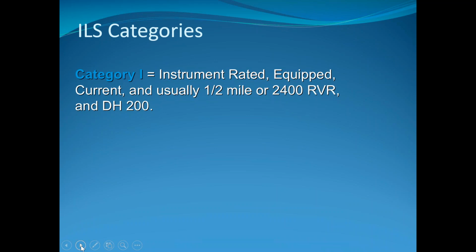But if you are going to an airport that has RVR reports available, the RVR is going to be the controlling visibility report. So if you see half mile or an RVR report, whatever the RVR says is the one that you have to go off of, if that makes sense. So if you're about to land and the pilot's checking the weather, or you as a dispatcher are checking the weather, and you see that the weather is below a half of a mile, let's say it's a quarter mile, then that means it would be below ILS Category 1 minimums.